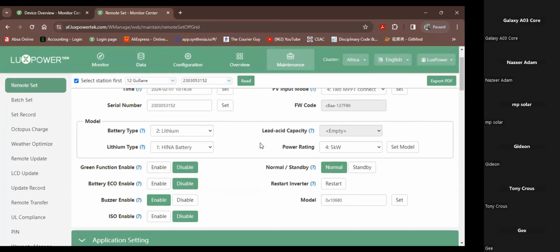Then I go into the inverter and set the battery on the screen by pressing and holding the enter button for 4 seconds, waiting for the spanner to appear next to the block with the numbers in it, going up to number 3, setting menu 3, enter, and then you select lithium, lead acid, or no battery.